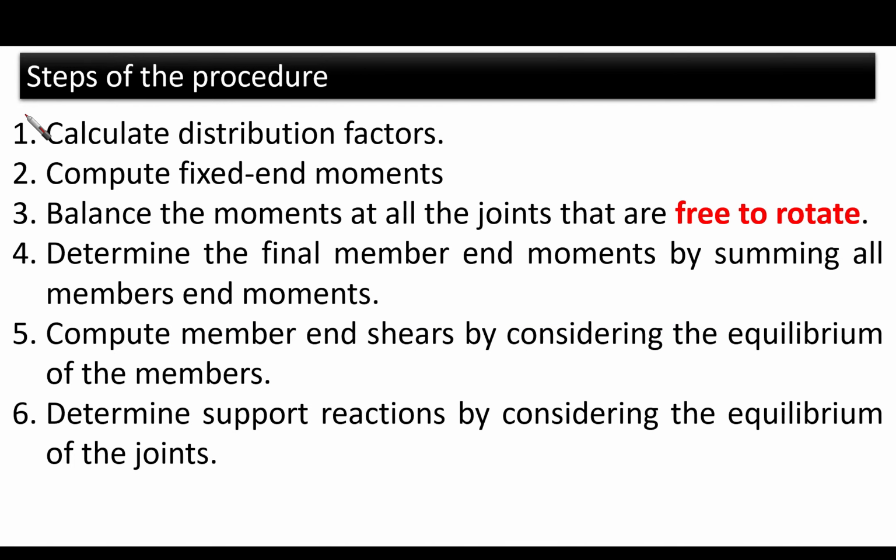First of all, we want to systemize this, to make it a system for us, or to put some steps for the procedure so that you can go through these steps directly to solve any continuous beam problem using moment distribution. First, we are going to calculate the distribution factors as we have seen in the previous video. Then we are going to compute the fixed end moments, second step, from the front or the back cover of the textbook.